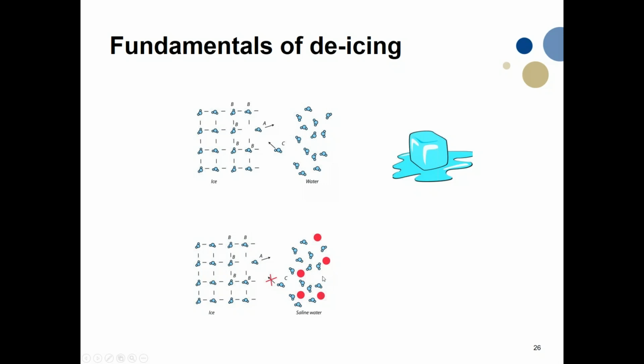So as the melting process goes on, we are more and more diluting the de-icer. At some point, it is equally interesting for a molecule to be here as to be there, and now the melting reaction stops. The freezing point has been climbing up due to the dilution, up to the temperature of the ice. At that point, we basically cannot melt anymore.